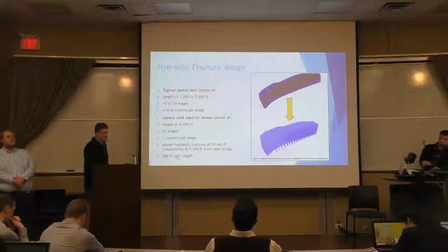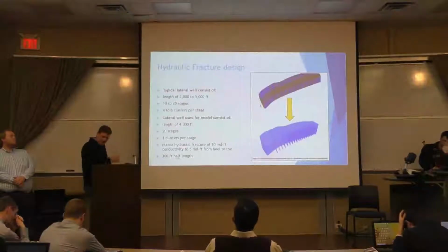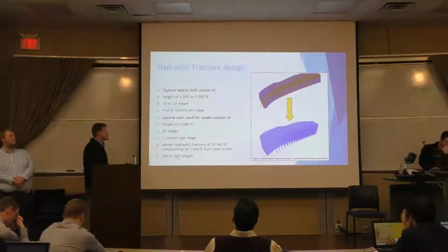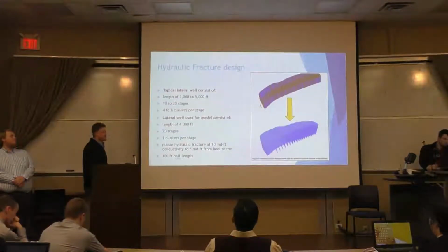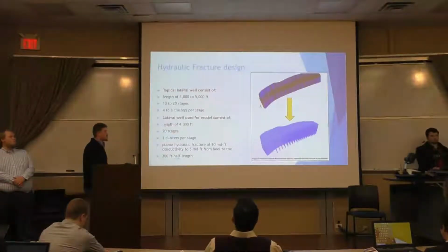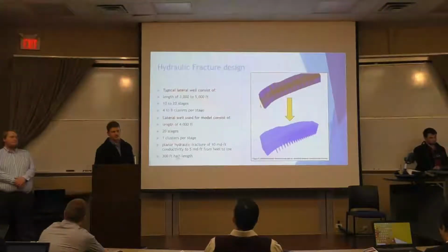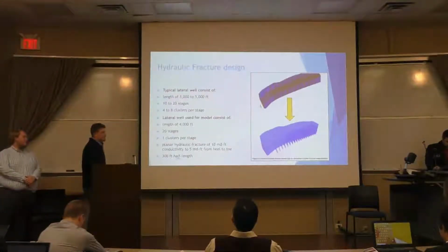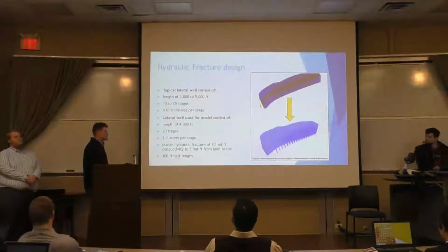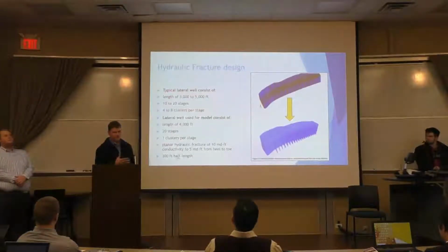Because, like I said, it was just for the injections, they still had to do a hydraulic fracture design for the shale. And instead of doing a complicated one, since a typical Eagle Ford Shale hydraulic fracture consisted of 3,000 to 5,000 foot with 10 to 20 stages and 4 to 8 clusters each, they decided to just do 4,000 with 20 stages and a cluster on each. They made the fracture length about 300 foot half length, with the hydraulic fractures being planar and having 10 millidarcy per foot at the heel where the fractures would start, and then about 5 millidarcies per foot at the toe.